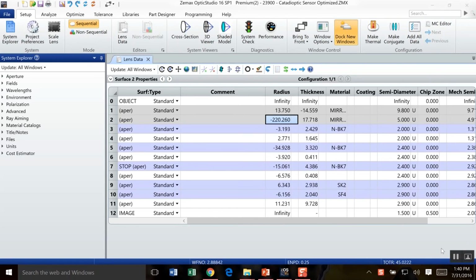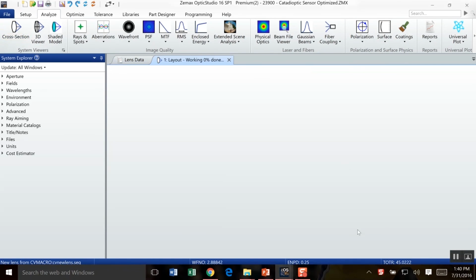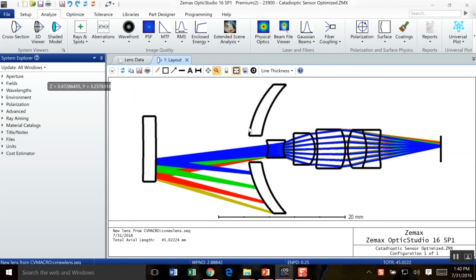If we go ahead and look at the results of that system optimization, just by looking at the lens data editor, there isn't anything that's too apparently different. We can see that we have added a slight curvature to that planar surface, planar mirror surface that is, following that optimization. If we go into the analyze, look at that cross-sectional view, again, I have added a bit of thickness to these mirror surfaces just by going into the surface properties and draw option. But other than that, everything's remained pretty consistent. Again, you can see that slight curvature that I mentioned earlier.